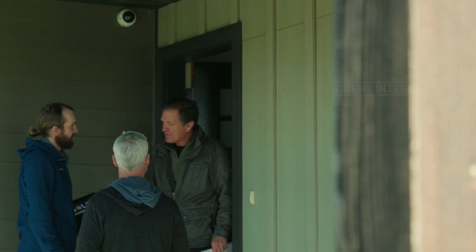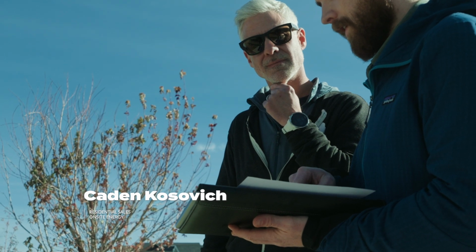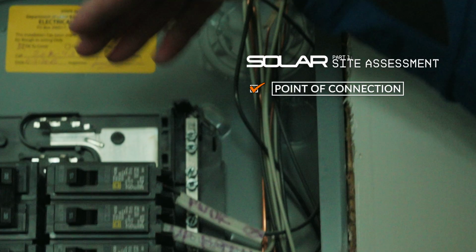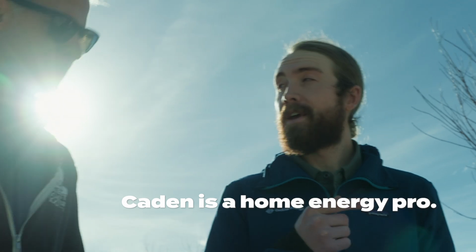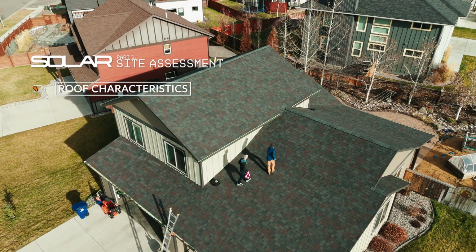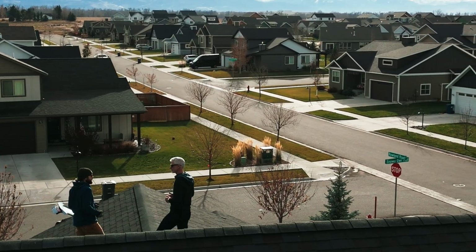I'll go inside, greet Rich. We're going to take a look at his main house breaker, which is in the garage. I'll take the dead front off that, document it, take some photos. We'll zoom out to the main meter panel, and then from there we'll get the ladder out and proceed to take measurements.